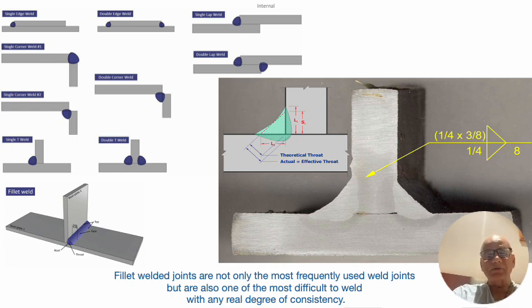As a primary observation, fillet looks to be simple to weld, as you see the entire fillet weld yourself, unlike the butt joint where we hide most of our runs in the subsequent layers and there is no visibility as to what is happening inside the groove. But any type of fillet joint, as you see here, whether it is a corner joint, single side, double side, or a lap joint, these are corner joints, but this is a classical fillet